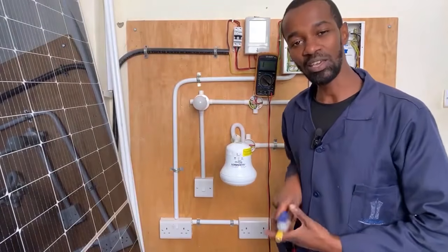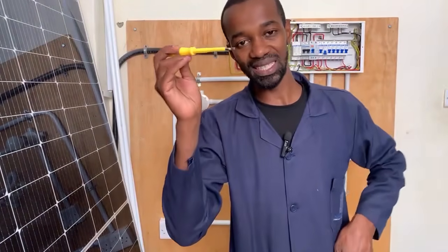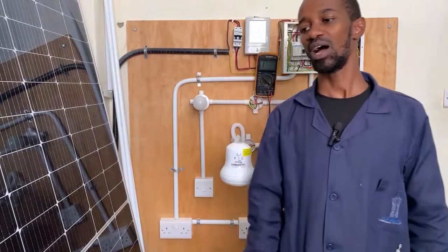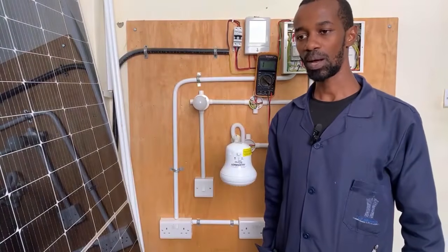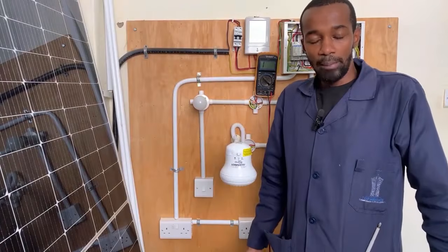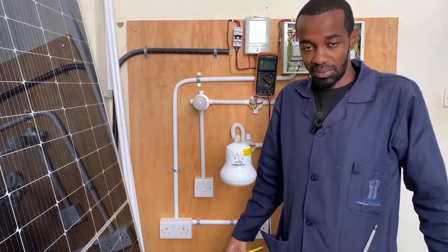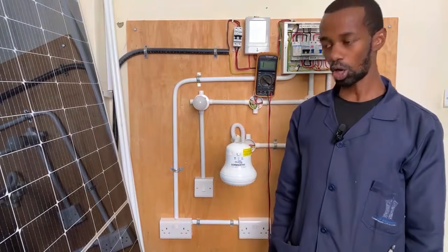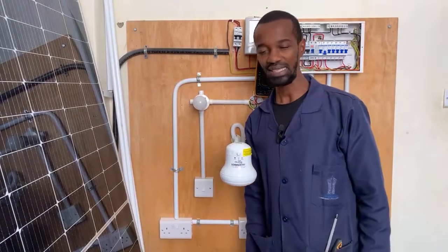My top boss, if you only work with this tester to go and troubleshoot, you'll have a very deep problem right there. How? Because you'll spend a lot of time on something that would have been sorted out very fast using a digital multimeter, doing continuity tests.